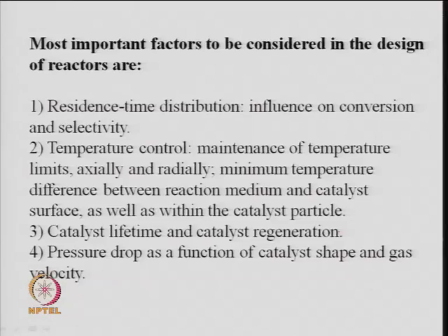The important factor, if you look at the reactor design, which I told last time also, is that whether it is a fluid bed reactor or a CSTR or a plug flow type reactor or packed bed reactor, we need to first look at the hydrodynamics, that is the residence time distribution inside the reactor. So, as I said, this RTD study is generally done by tracer concentration, right. Now, radioactive types of tracer materials are used, right. And so, the idea is that we are trying to find out the concentration down the length of the reactor under the given condition, right.